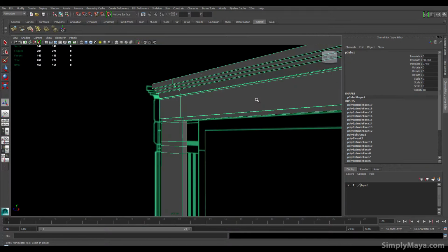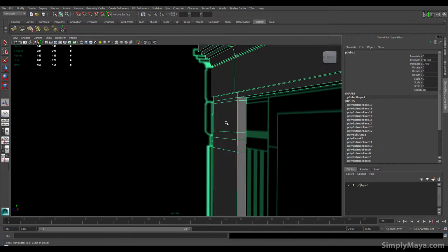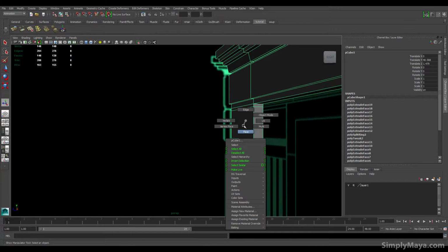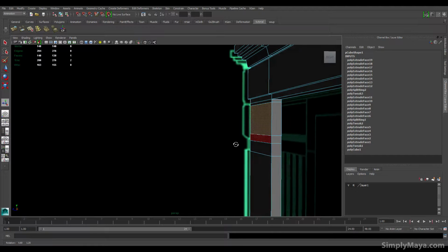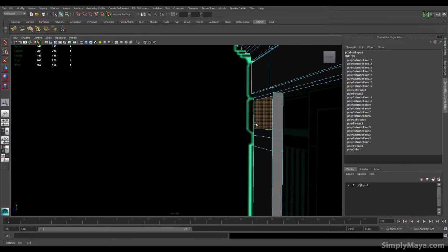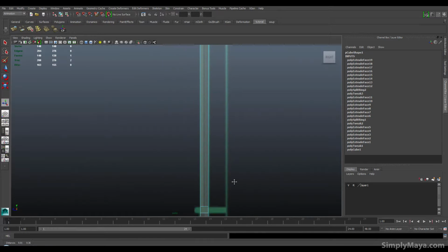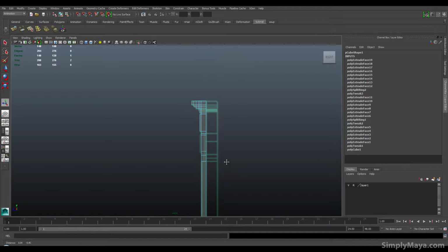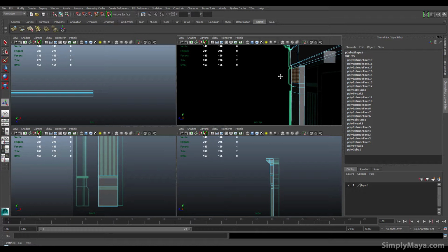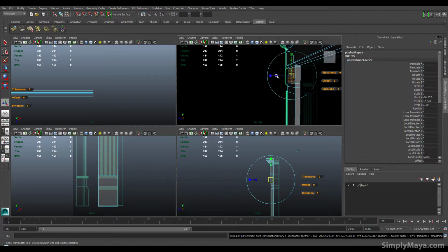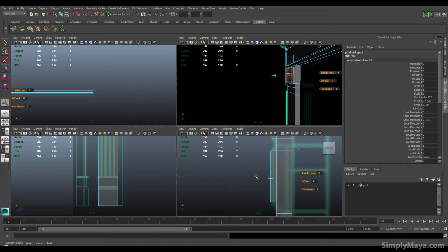We're doing the whole thing with an extrusion. We've added one or two edge loops, but predominantly this is just really an extrusion. So let's grab all the faces that need to come out. So this one, kind of, and let's see here. In fact, let's go into the side view. It's a bit easier, just so I can get a look at what I'm making. All right. Perfect. So this one first, let's pull that out, G, and let's get it sort of the same distance as that one up there.